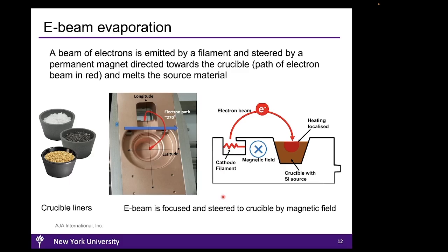Electron beam evaporation, however, is an alternative to thermal evaporation. Specifically, this technique uses a focused beam of electrons to melt a target material locally. Because of its operating mechanism, electron beam evaporation provides two advantages over thermal evaporation. First, it extends the range of target materials that can be deposited. Second, it provides higher purity due to local melting of target materials.